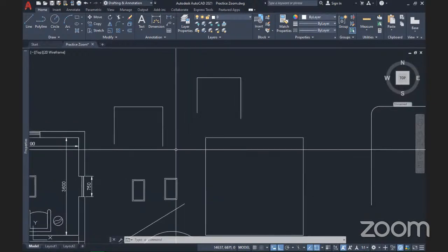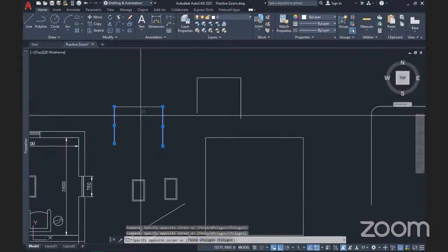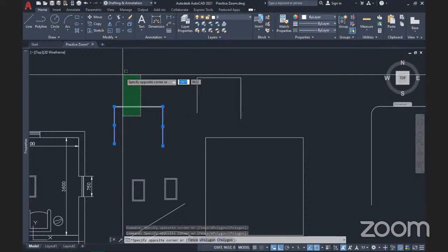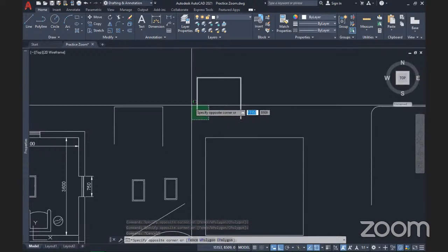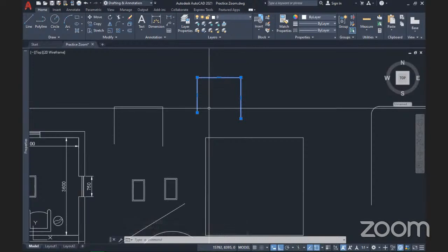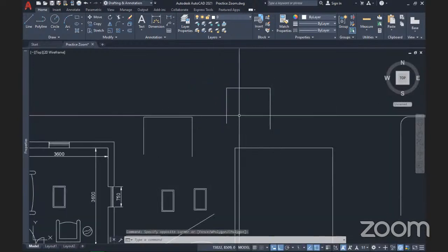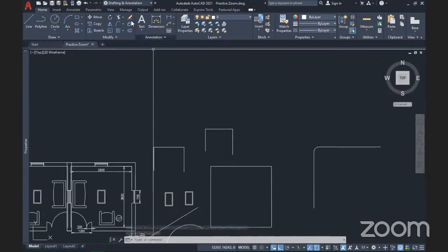Okay, now let's explore the difference. For the line command, if you highlight any of the lines, you'll notice that they are separate from each other. They are not tied together, not joined together. They are all segregated separately. But if you try to highlight one part of the polyline, you'll notice that all the parts are connected. All the segments of the polyline are connected, hence the name polyline. So having explained that, I will come back to this. I will use the fillet also to explain that.